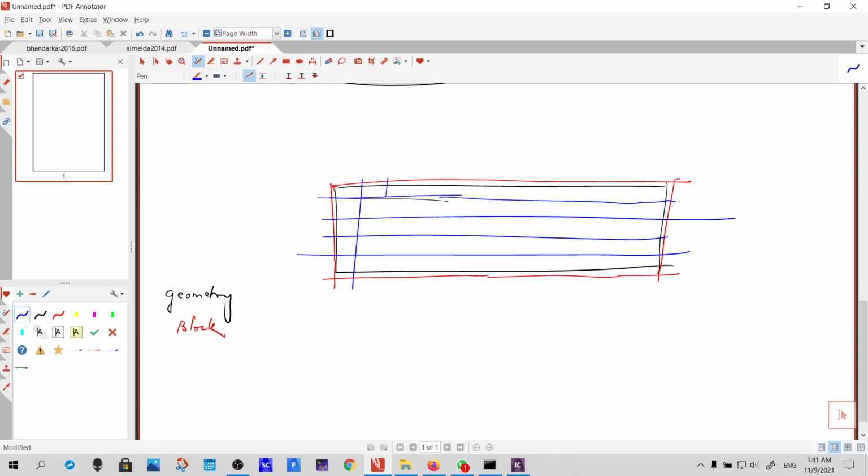We can simply give parameters and generate a mesh. But there are basically two reasons. First is mapping, of course, but this has already been mapped, so it doesn't require mapping at all. The second most important factor, which people ask about, the main reason for these kinds of geometries, even for simpler geometries, why this blocking association is required.